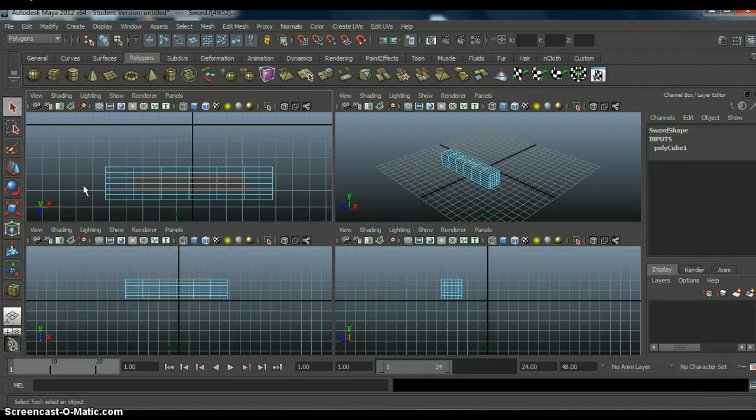I've selected both of these rows and they are now highlighted in a yellow-orange. If you look down here in front view, you can see that the bottom of the polygon also has some faces selected. Normally Maya does that if you use the selection box, so that's no worry. In fact, that's exactly what I want us to use to extrude. I want us to extrude from not only one side but both. So let's get into that. Oh no, looks like everything is good to go.